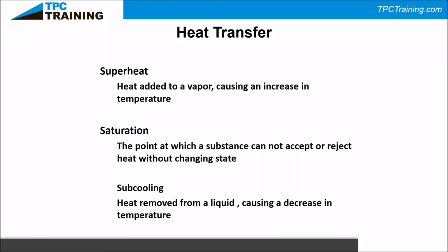To diagnose your system, one small example, and Ryan, you remember you were having issues with your air conditioning system, and I mentioned to you, if you take a thermometer and put it on the return air of your ductwork, and then move the same thermometer to your supply, you should see about a 15 to 20 degree drop in temperature. That's a good sign that the system is charged close to where it needs to be. But to dial it in, the best option would be to use superheat and subcooling. So you're going to weigh the charge in, if it's empty, full evacuation, weigh the charge in, and then use superheat and subcooling to make sure it's where it needs to be. So it depends on the situation, Ryan, and what's going on.